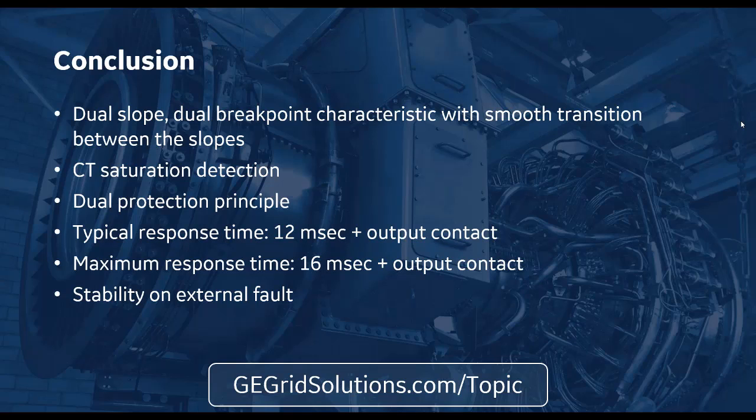And I've seen a lot of misoperations because of people paralleling CTs into differential protection. Except, as I said, you might think about doing it, even then it's kind of iffy, if you have two radial feeds and for any fault in the system only one of them is going to see fault current, then it's not ideal, but it's okay to parallel the CTs. But not to say people don't do it.